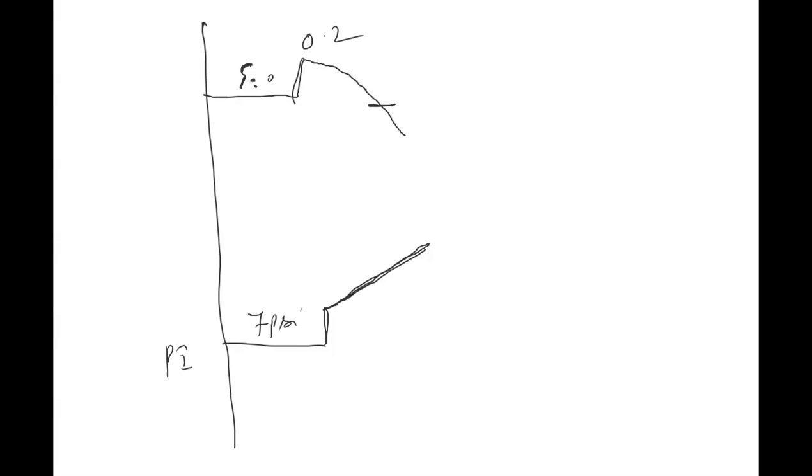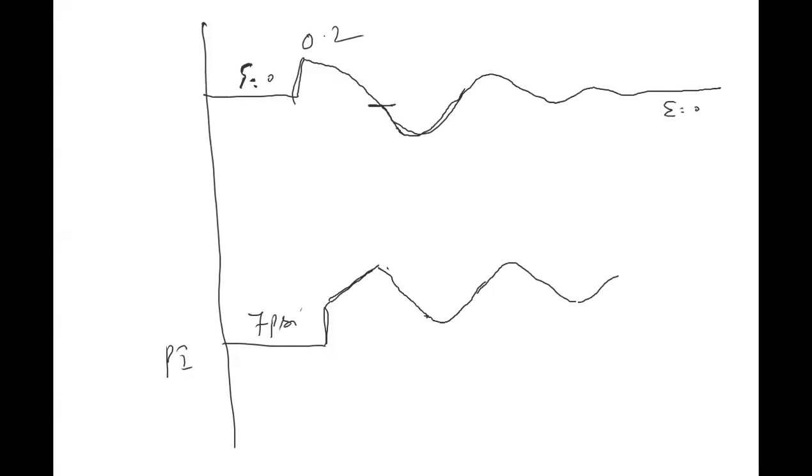This is the reality that I am saying. Pressure keeps on increasing. When the error becomes negative, it will slowly decrease. Then the error will slowly make a U-turn, and once again it increases. So in reality, you will get an oscillatory response where slowly the error becomes 0. That is where the pressure signal will also oscillate and finally settle at a new value.